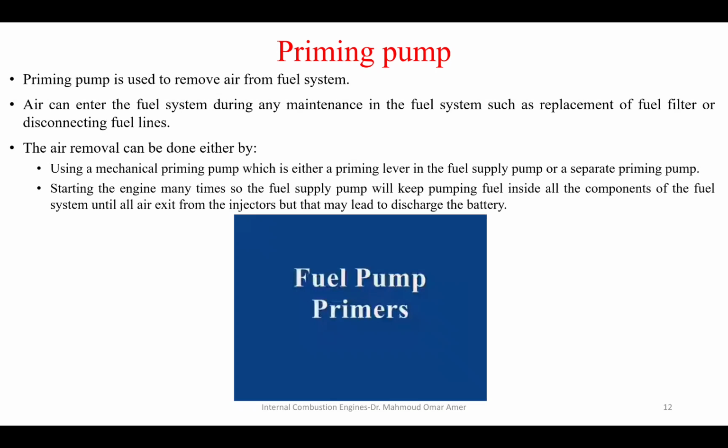We need to remove air from any fuel or fluid lines. Why? Because any existing air in the fuel lines, especially in high pressure systems, will cause cavitation problems. And we know that air is compressible, while fuel liquids are incompressible. So if air exists in the fuel line, what will happen when you try to increase the pressure?